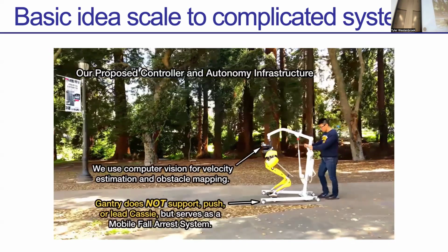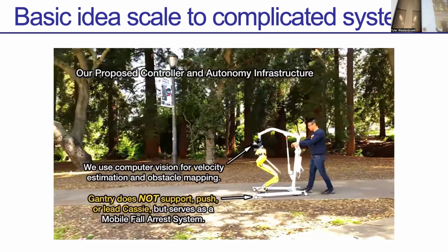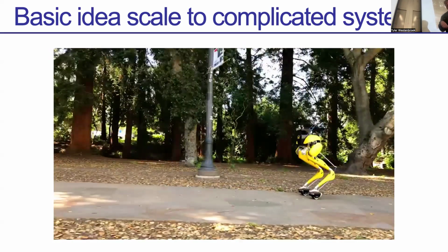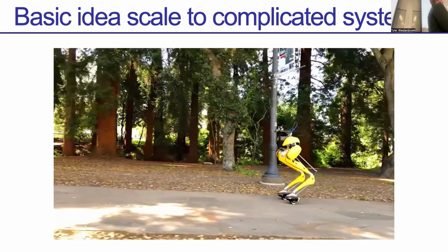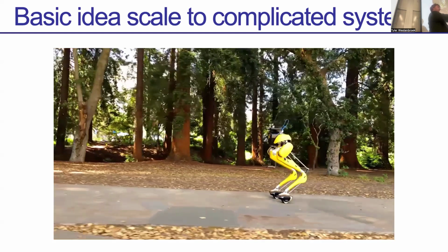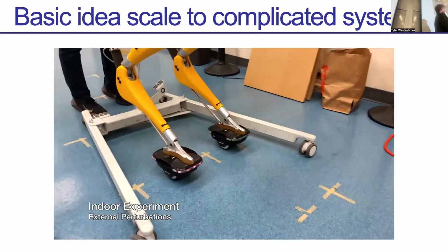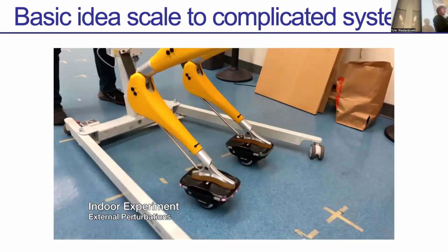This is a very high dimensional system. There's a lot of things going on with it. But really what they did is they broke down the system in the way we're going to today, where you generate a plan for what you want to do. In this case, it is keep my robot upright and move forward at some desired velocity. You generate a reference, and then you design a feedback controller, which tries to keep you on that reference.